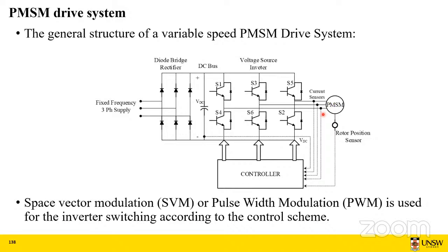Whereas in an induction machine, a rotor cannot rotate at synchronous speed, because if it did, there would not be any induced voltage or current in the rotor, and it would fail to produce any torque. In a synchronous machine, we are not inducing any current or voltage in the rotor. We are supplying it through the field winding. That's why it can rotate at synchronous speed.